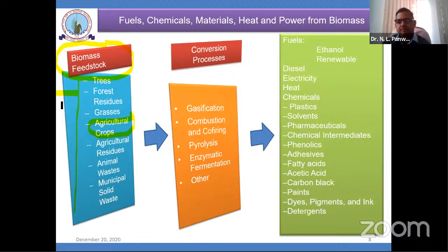We have discussed gasification and combustion, and co-firing. If you go through the MNRE website, you will find that they are promoting co-firing in cement industries. Up to 2%, 3%, or 5%, whatever crop residue or surplus biomass is available in the vicinity of the cement industries is mixed with pet coke or coal, so they can supplement some of the fossil fuel without affecting the overall production.